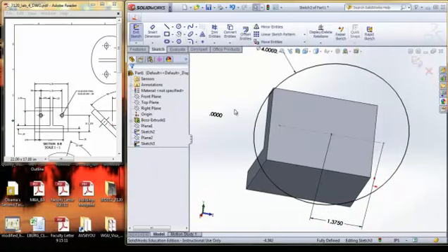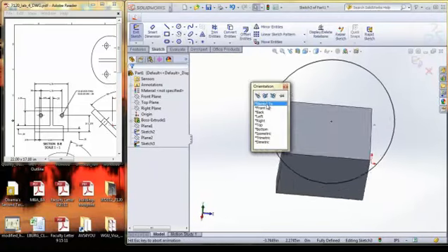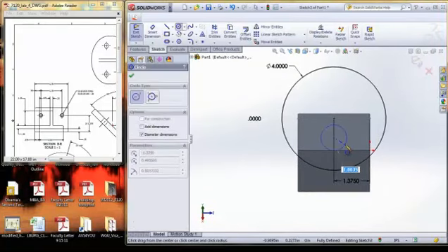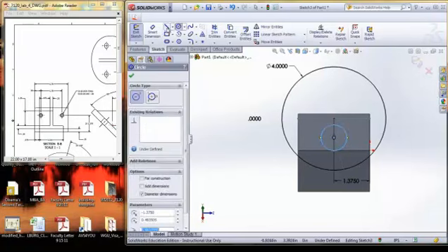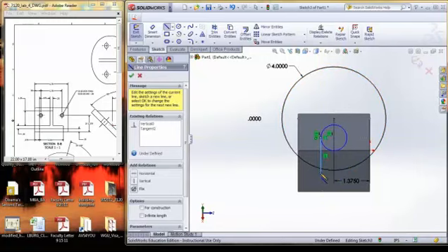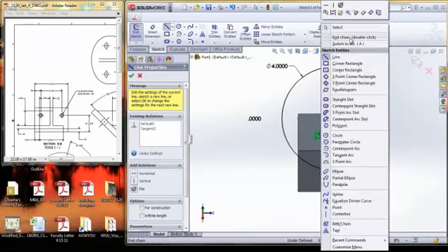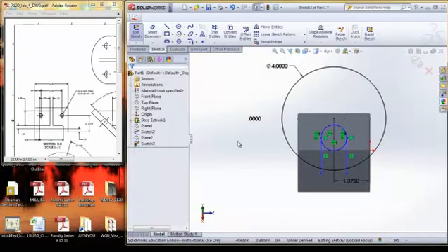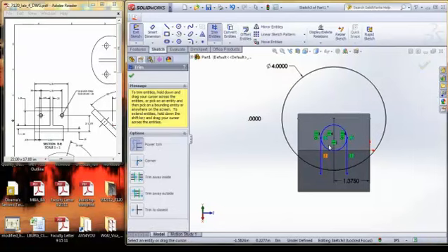Now, maybe this would be a time to go to the normal 2. Draw a circle that will be lined up here. Might be kind of big, but we don't care. Okay, we'll go in there and draw a line there. Right click, end the chain, come back over, right click in there again, and just select because you're done. Then I want to trim. I'll trim this out, this, and that.